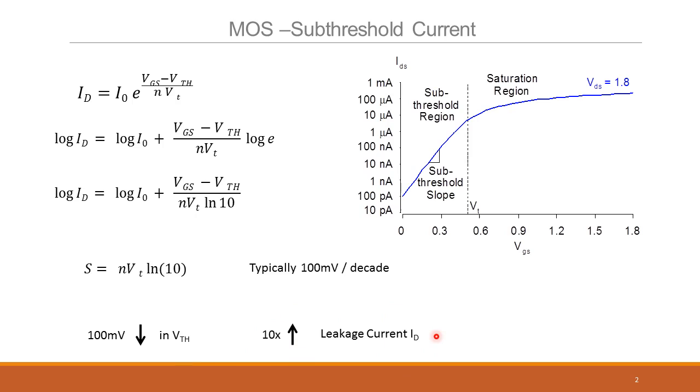The reason for that is if you scale VTH too much below, the leakage current, the current that the off transistor takes, will increase. And you don't want that because if there are billions of transistors sitting there which are supposed to be off, but each leaking a large amount of current, you'll find very soon that the active power is much smaller than the leakage power. So leakage current has been one of the biggest problems to solve in digital ASICs in the last 5 to 6 years, or maybe even 10 years.